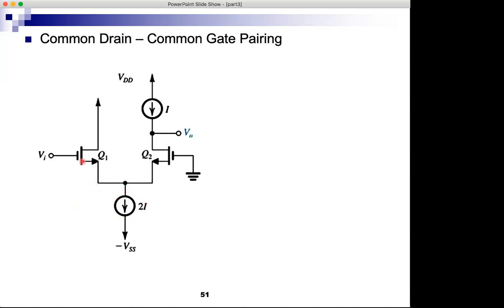So in the signal analysis, I have this wire, and the signal goes from the source of Q1 to the source of Q2, and this is the intermediate output between Q1 and Q2, and I get the signal here, and this is the input for Q2. Q2 has gate at signal ground, and then the output from the drain, and this is common gate. We call this common gate.